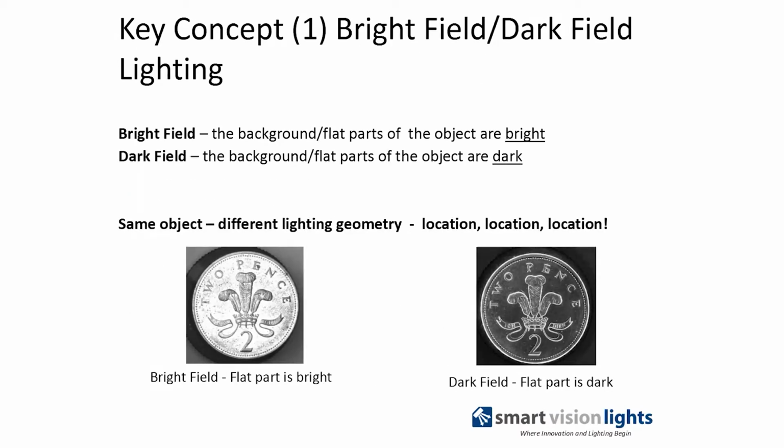So as we enter into concepts of lighting, we're going to talk about bright field and dark field lighting. And today, again, we're going to focus on the bright field aspects. So bright field means, as the name implies, the part is bright. If light hits the surface, it's reflected off the surface into the camera and causes the pixels it's hitting to become brighter. Dark field is just the opposite, and it's less intuitive, but in dark field the flatter surfaces reflect light away from the camera, and only edges or things with angles reflect light into the camera. So basically you get an inversion between these two.